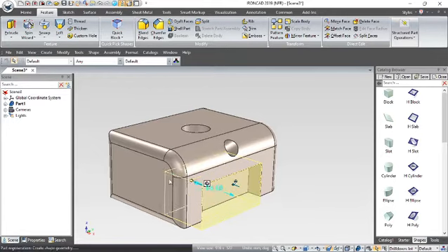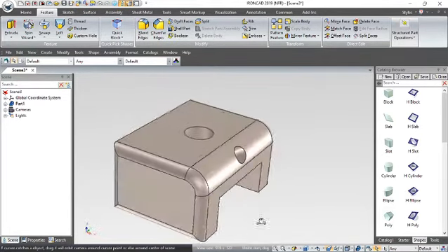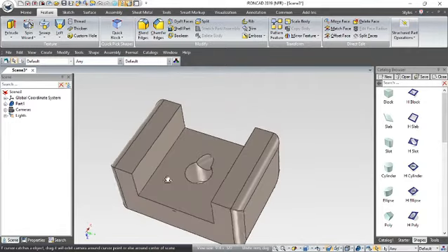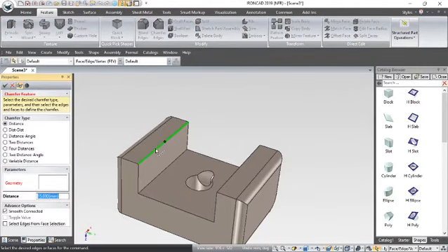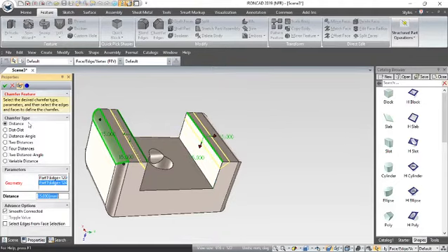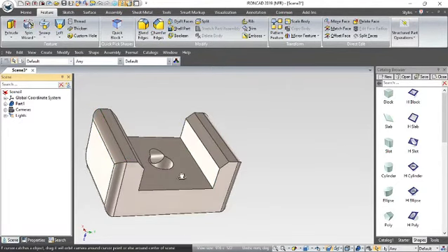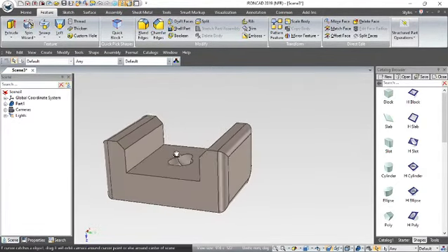And what I'll do now is drag that through here like so, and you can see it's very quick. We're not doing any sketching at all here, we're just using the shapes that are in the catalogue to create these features. Again here, maybe I want to put a chamfer edge on this edge here, so I pick that one, and that's currently at 15, so I'll leave that, pick that one there and just go OK. So that's how easy that is.